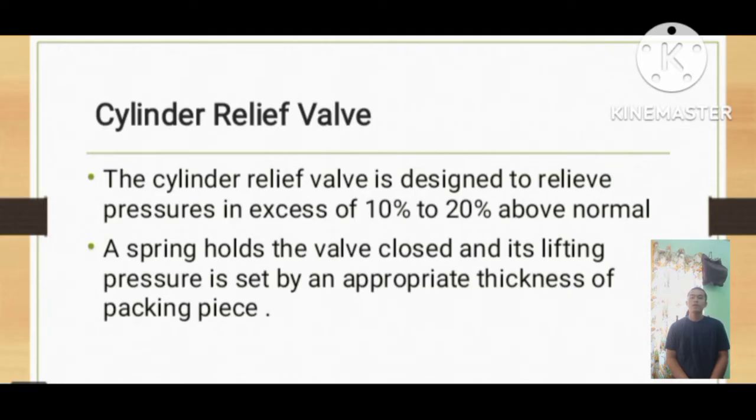First, temporary measures. Either leaking or lifting of the relief valve should be considered a serious issue and should be investigated. If the ship is maneuvering, the engine cannot be stopped, so temporary measures can be taken below. Rotate the spindle on its seat until the leakage stops.